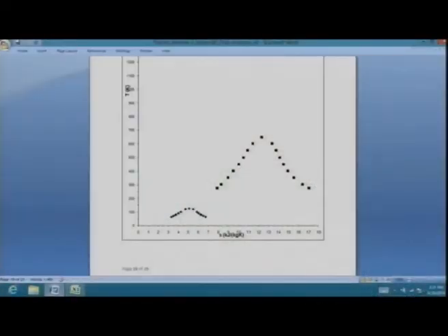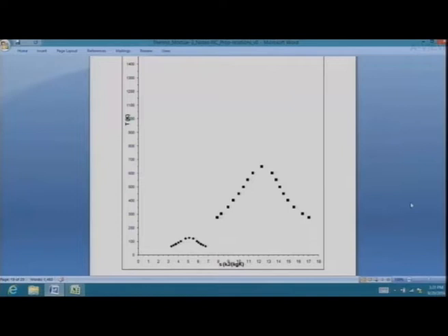If you make the plot for nitrogen, I'll show you a picture. What I've done here is something beyond what you see in the charts, in the sense that I have equalized the reference condition for nitrogen and water. I said that the specific entropy of both substances at 0 Kelvin is 0.